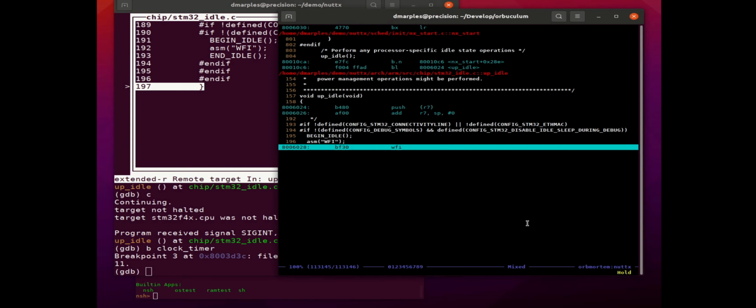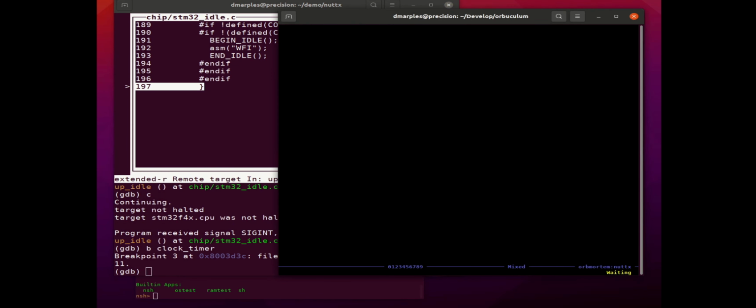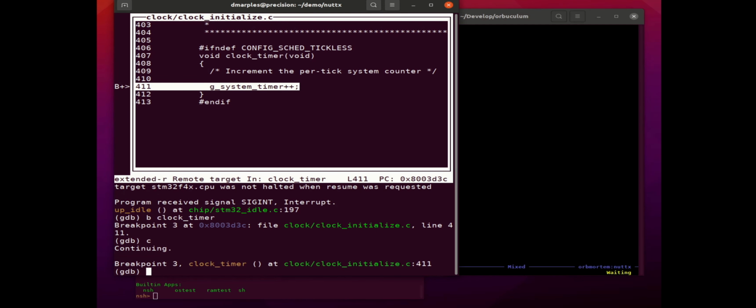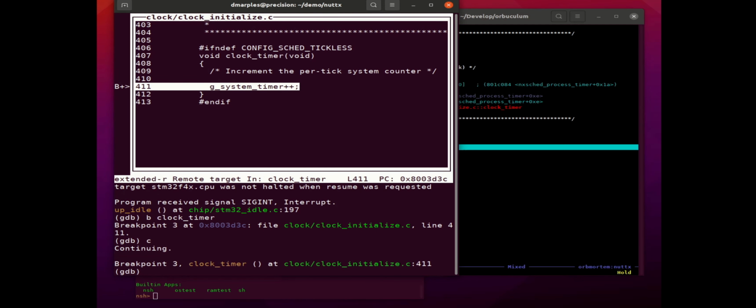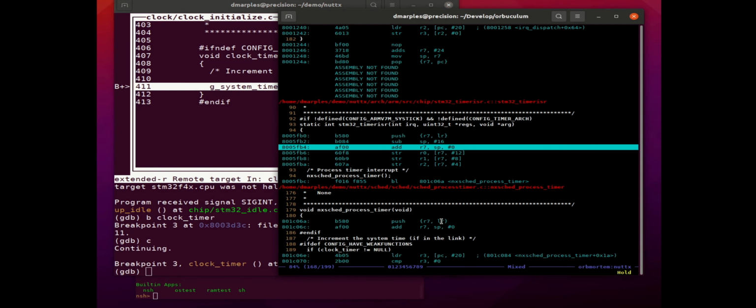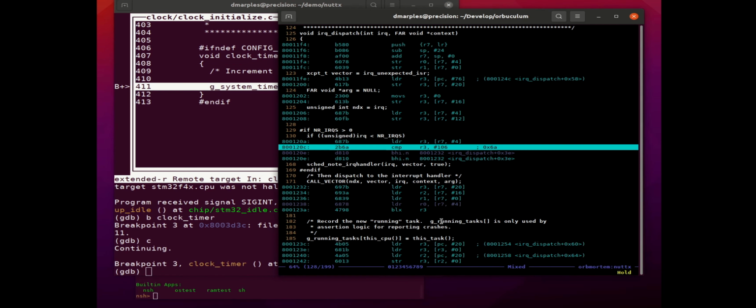Okay, we've got a break in there. Let's unhold it. So it's now waiting because there are no instructions coming in. It doesn't know what to do, so it just sits there waiting for some instructions. And I tell the program to continue. It runs for a very short period of time, and again it hits the break point. And now what I've got is the history of the instructions until that point in time.